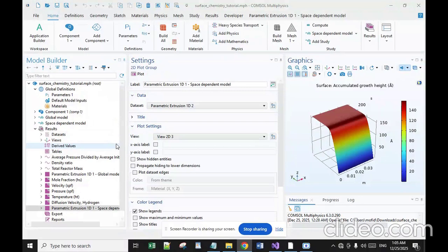The processes listed below are not commercially viable yet. As for the carbon source, the most popular carbon source used to produce graphene is methane gas. One of the less popular choices is petroleum asphalt, notable for being inexpensive but more difficult to work with. Although methane is the most popular carbon source, hydrogen is required during the preparation process to promote carbon decomposition on the substrate. If the flow ratio of methane and hydrogen is not appropriate, it will cause undesirable results.